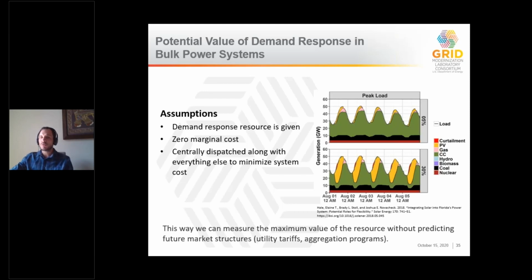A simplified approach could be to optimize dispatch using price data generated by the grid model and then feed the net load impact of that optimization back to the grid model to evaluate the resulting change in operating costs. This simplifies the inputs to the grid model, but assumes that flexibility dispatch won't substantially impact electricity costs. An even more simplified approach would be to skip optimization altogether and simply apply discrete demand response scenarios to the building stock models to determine the net load impact and then feed the corresponding net load shape back into the grid model. Next slide.